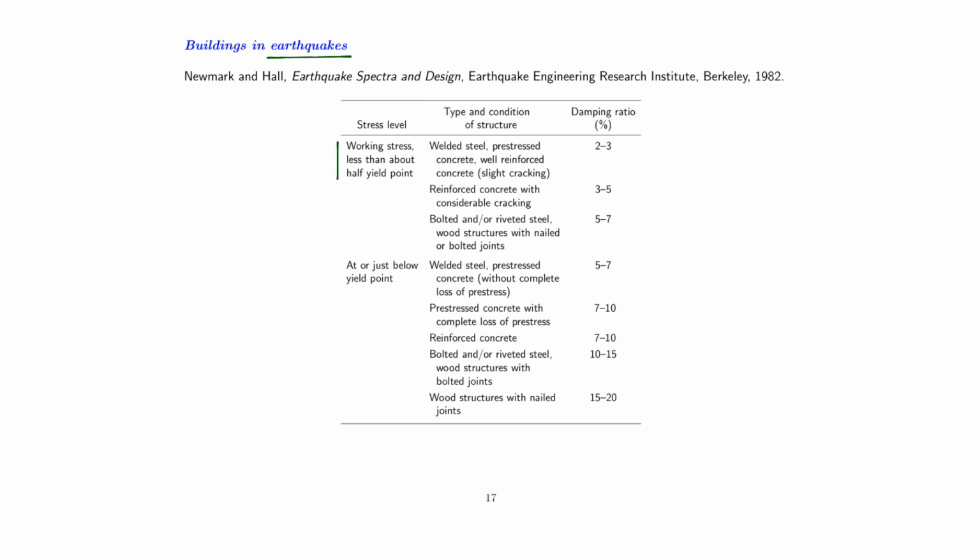So when you are beyond yielding, you will have the order of magnitude that we discussed previously, but once you approach the yielding point, you will of course dissipate much more energy, because yielding is associated with material damage, and that is energy that simply disappears out of the structure, and suddenly you have totally different levels of damping ratios.